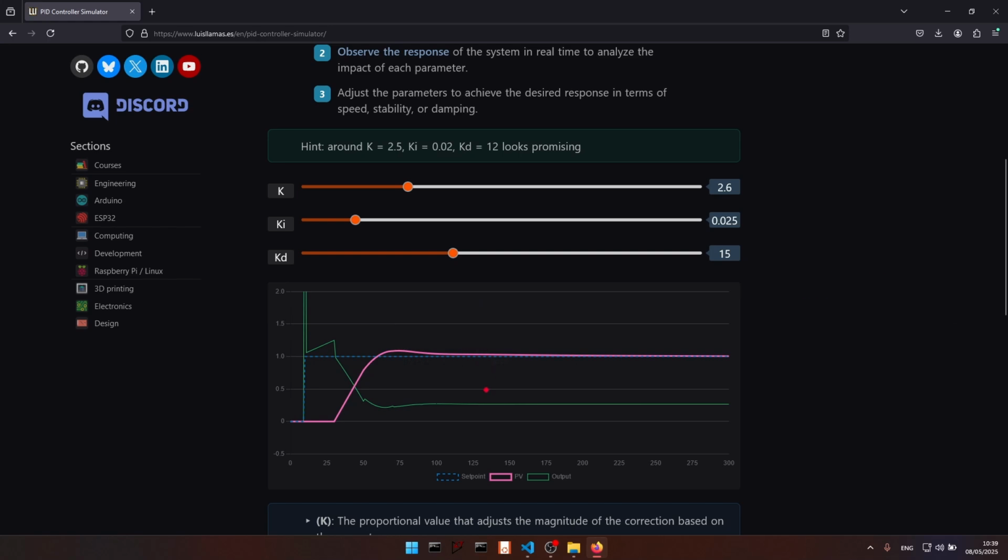Step 5 is do any fine tuning you need to do. So what fine tunings can we do? Well, firstly, you can see there's a bit of an overshoot and there's a bit of an offset. Can you see how the PV signal, once it overshoots, takes a while to gradually get down to the set point? So what we can do here is reduce Ki. By reducing Ki, we bring this PV, or the pink signal, down to the set point.